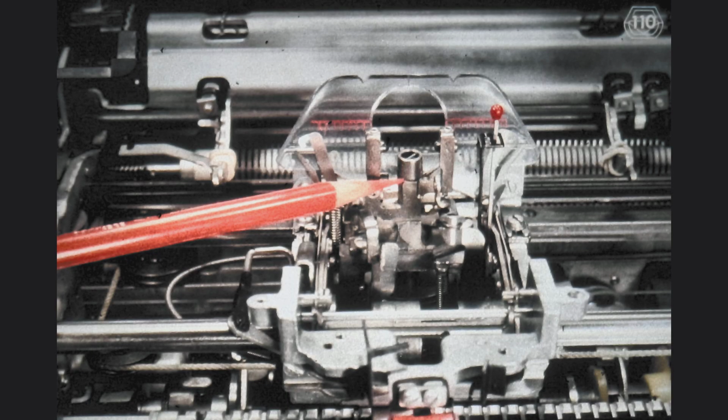When we position the rotate pulley back onto the bottom of the rocker, we have two dimensions to consider. One is the angular position of the rotate pulley, which we will take care of later, and the second is the vertical position of the pulley on the rotate shaft. We should position the rotate pulley on the rotate shaft so that the shaft has approximately 1/10 of a millimeter of end play.